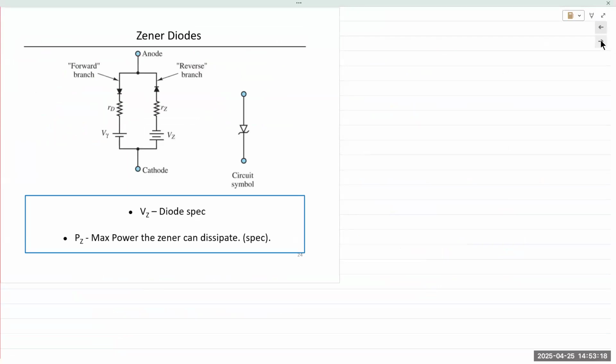So the property of a PN junction is that if you apply an external electrical field with the positive polarity to the N-type material and the negative to the P-type material, we say the junction is reverse bias. The minority charge carriers are actually attracted away from the junction.